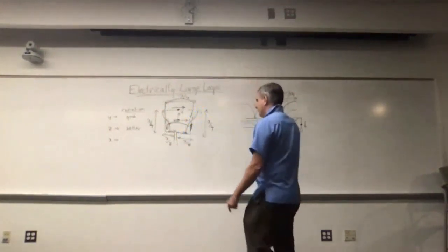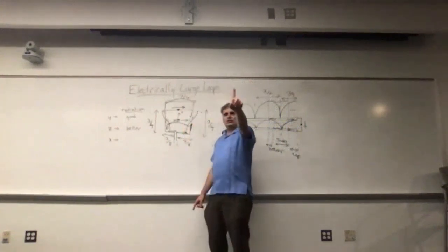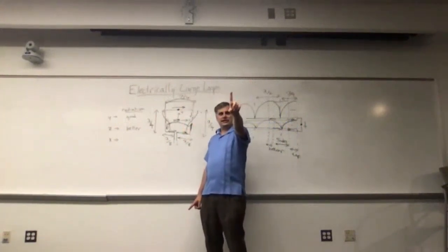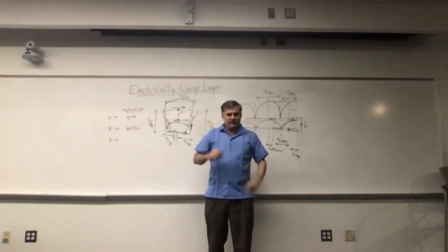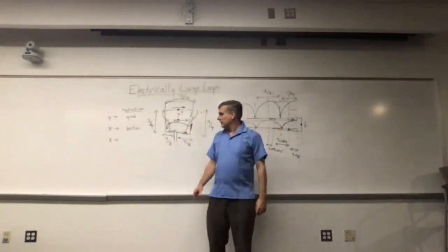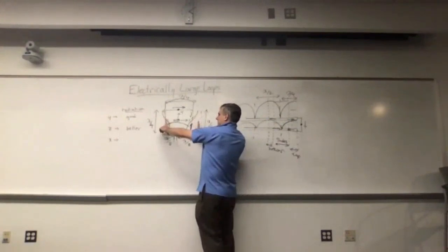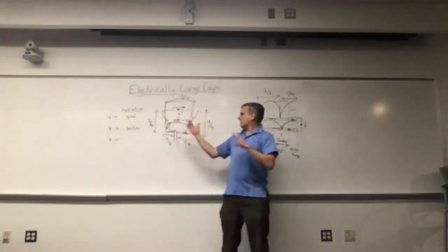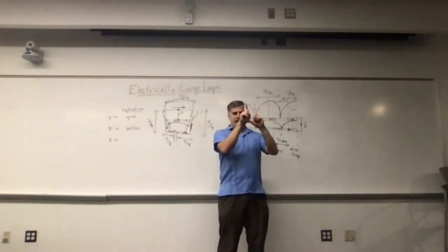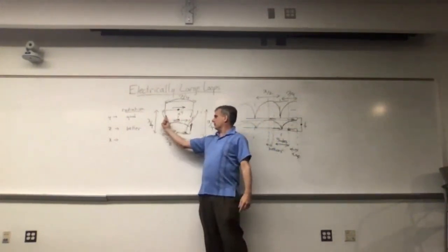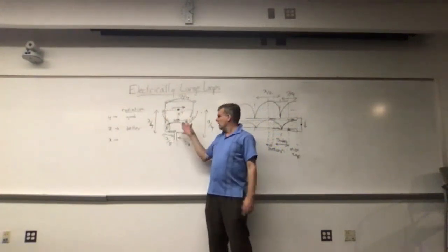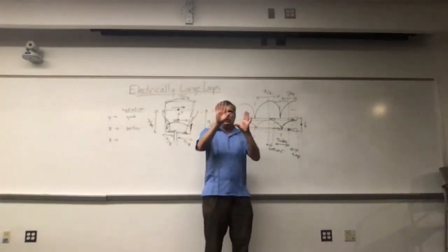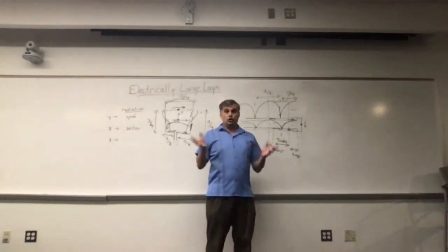However, let's say you take a vertically polarized source like this, you hook up your little receiver and your little headphones and you listen to the beacon transmit. Take your loop antenna and use it in this configuration. You hold it out and you're trying to listen to vertical polarization. These won't contribute because they're horizontal, right? Aim your deep null towards that source. You shouldn't hear it.